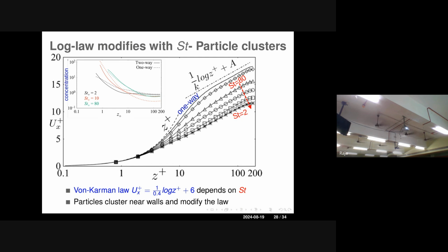We try to track and sense that. Possibly, if you are varying the Stokes numbers in the system, each layer may have different concentrations. So in your turbulent flow, when particles are suspended, based on their heaviness and so on, the concentration distribution of particles across those logarithmic boundary layers also changes.